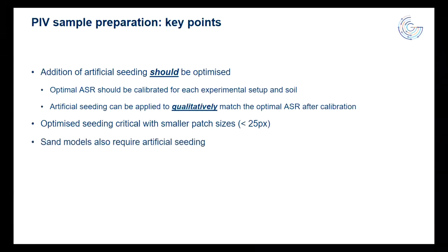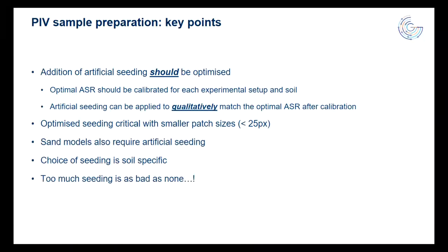Sand models also require seeding. It's worth the time and effort to add the seeding to sand as well, but the choice of seeding is definitely soil specific. The final takeaway is too much seeding is as bad as none, right? So you don't want to make the mistake that Raf and I made by applying what we thought was an optimal amount of seeding, then getting into the centrifuge, back saturating with methacel and finding actually, because we hadn't mocked up the whole experiment in all of its detail, we ended up with bad texture in the first experiment we performed. So mock up your tests exactly as you want to perform them in the lab.